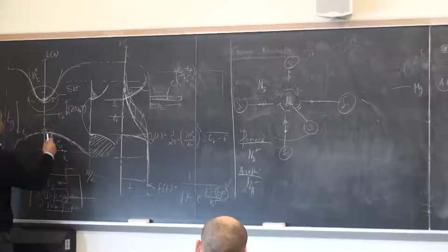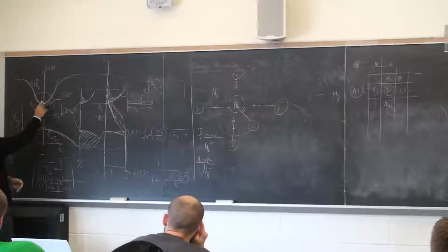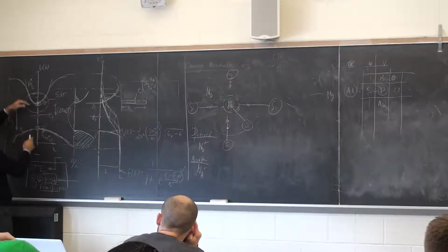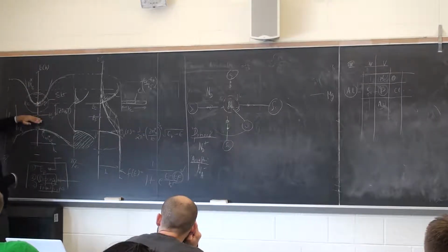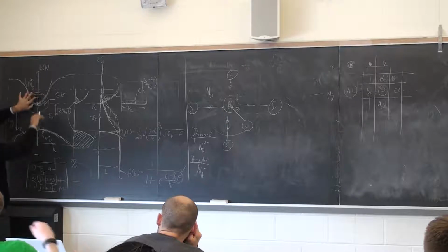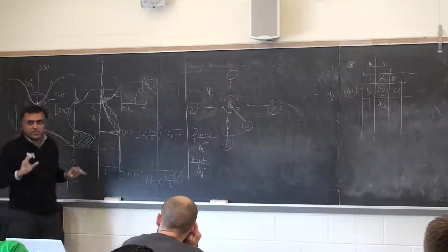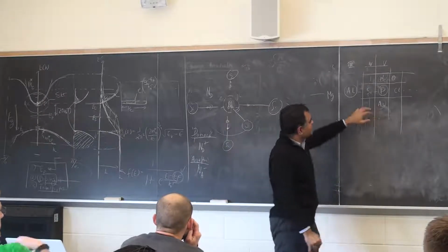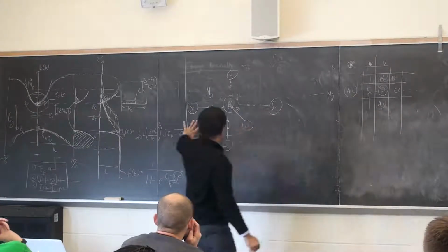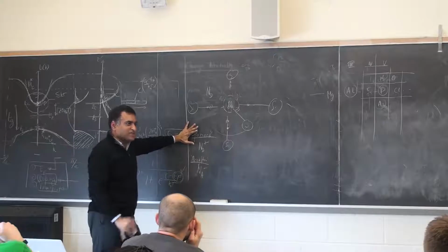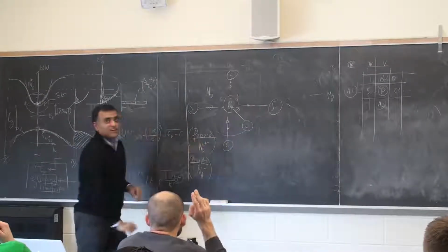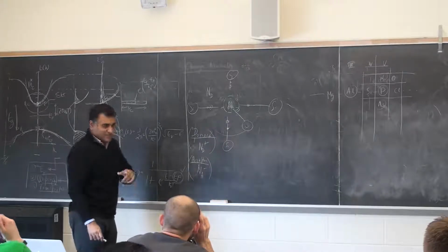If I put phosphorus in gallium arsenide, or nitrogen into gallium arsenide, the state is here. It's inside a band, not even inside the gap, in which case it splits the band into 2 and all that sort of thing. So it can have many ways of creating the electrons or holes. The one I'm telling you is kind of the simplest, and it's the most used. Okay, so acceptors become charged, donors become charged this way.